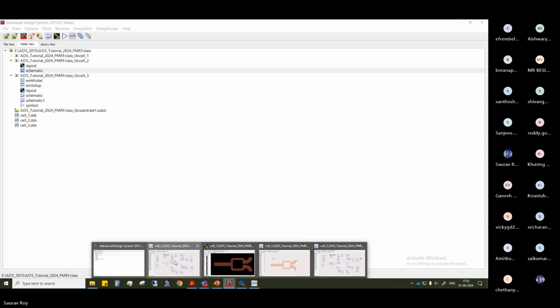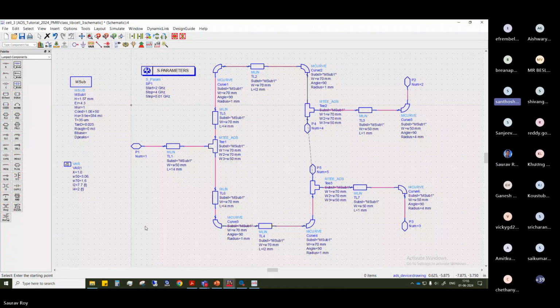Okay, what is the use of mesh? I don't know if you have read about electromagnetic simulation or not. These are called computational methods, which can be done through FDTD, method of moments, or finite element methods. Those methods calculate the surface current or voltage or electric and magnetic fields, and based on that, this 3D EM simulation is carried out.